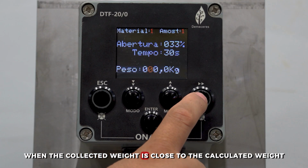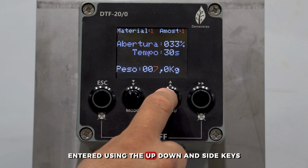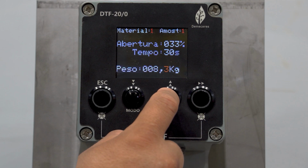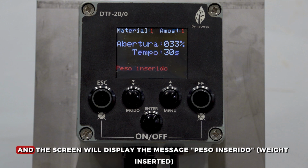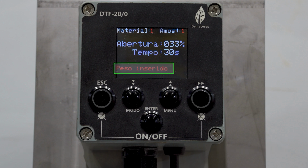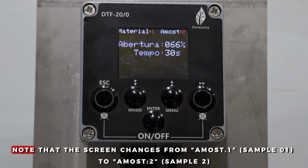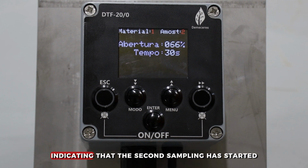When the collected weight is close to the calculated weight, the weight must be entered using the up, down, and side keys. After registering the weight, press the Enter key to save it, and the screen will display the message, Peso inserido. Press Enter to confirm and start the second sampling. Note that the screen changes from Amostra 1 to Amostra 2, indicating that the second sampling has started.